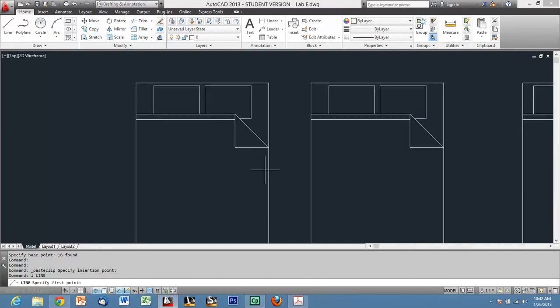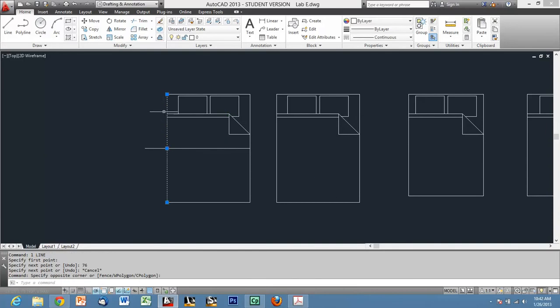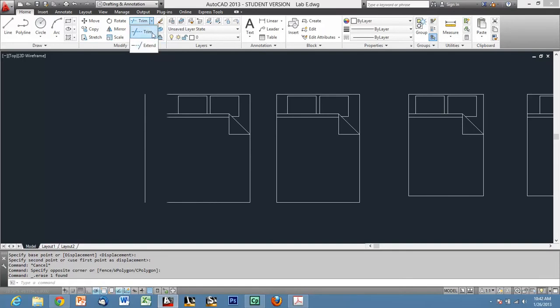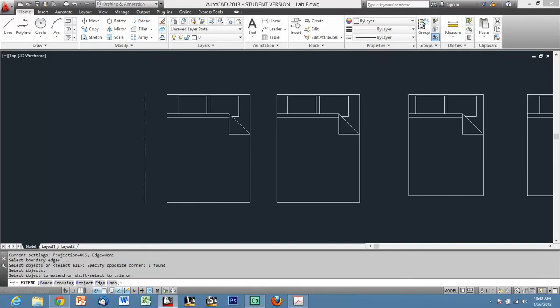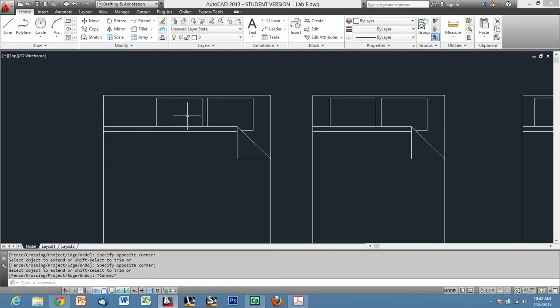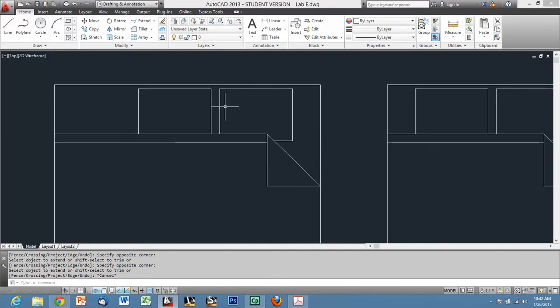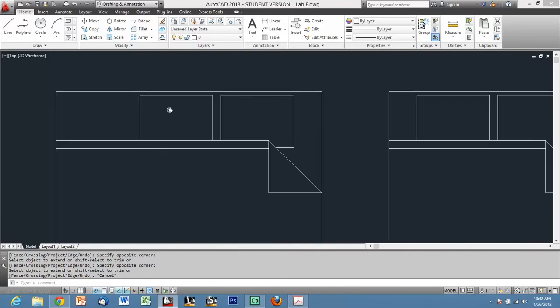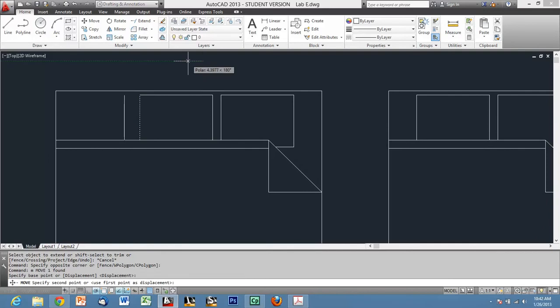And this needs to be 76 inches wide, so I'm going to put in a construction line and take everything here and kind of stretch it out. And then I'm just going to use the extend command to take these lines and lengthen them all up. And finally, if you'll notice, most king-size beds have a larger pillow size because these little tiny pillows look kind of funny on there. So I'm going to take these pillows and make them about 6 inches wider at the same time before I center them up.